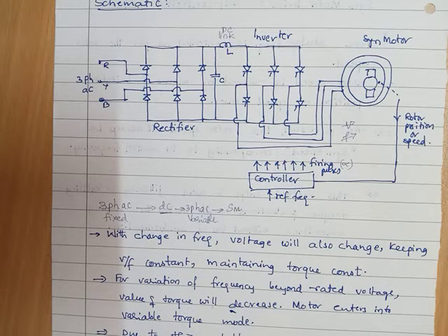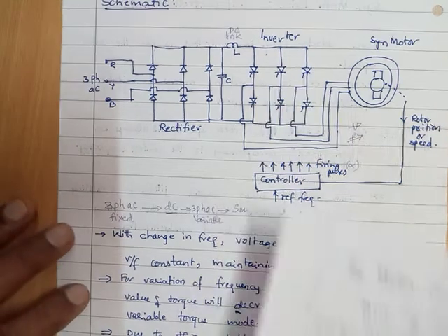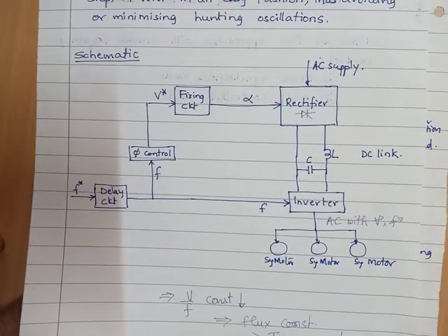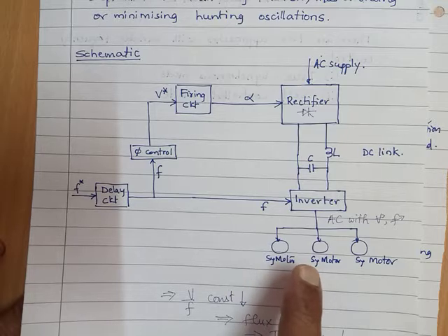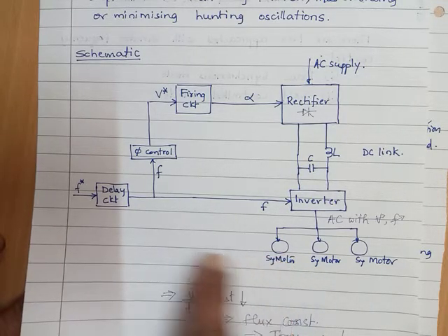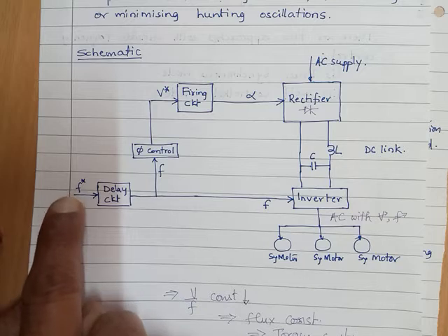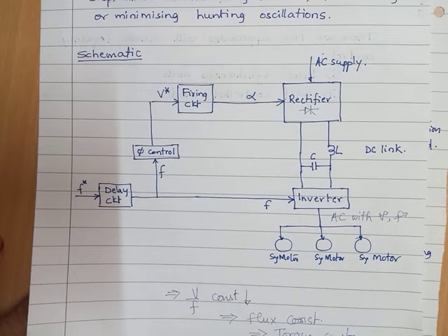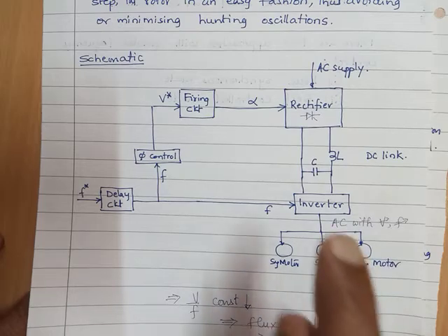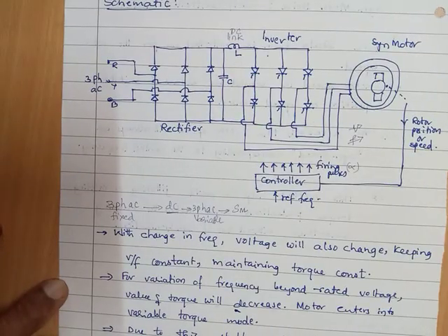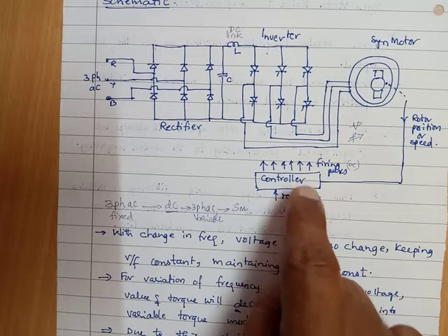You compare that with the true synchronous mode, wherein the approach was different. The motor speed was not monitored. Instead, the frequency was generated using an independent oscillator. That's why, compared to this method, the self-controlled method is smoother.